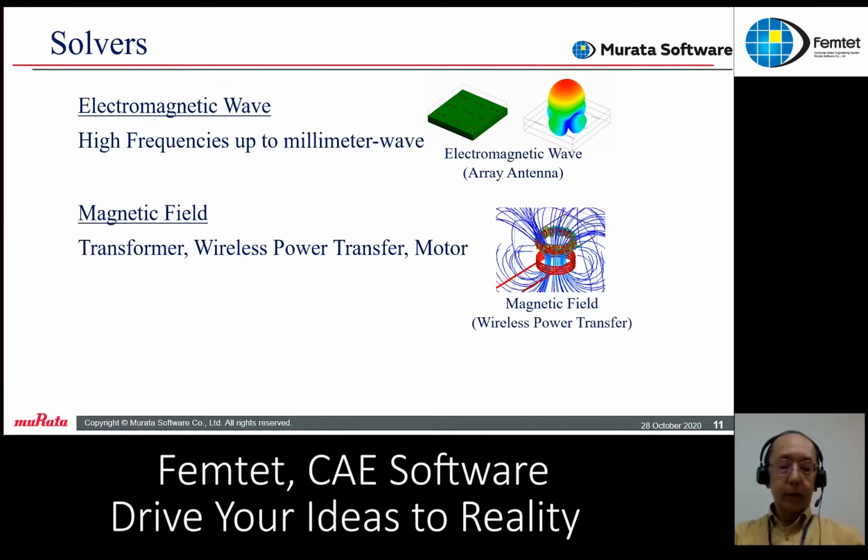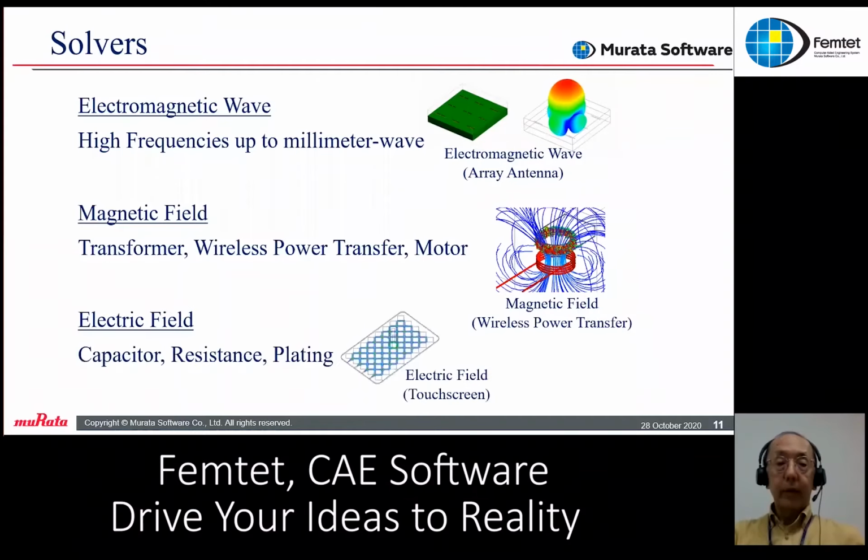Next is the magnetic solver. It solves the magnetic fields generated by running current or magnet. You can perform the transient analysis of magnet, coil, transformer, and motor.